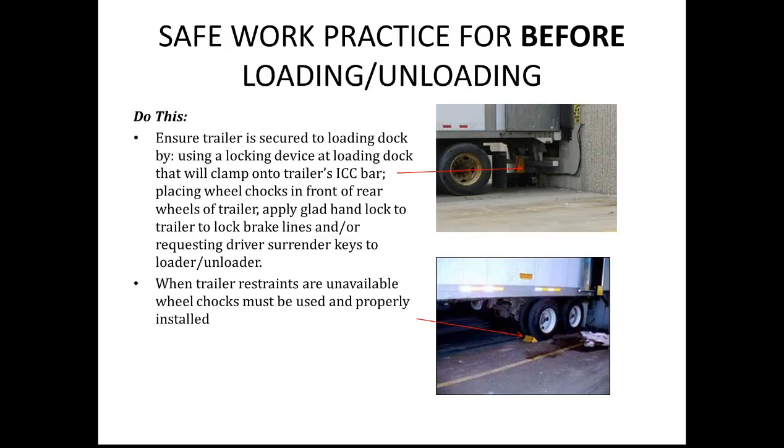The second is that you can place wheel chocks, and you see where that steel wheel chock is in the second picture. It's put behind the second tandem axle. That's where you put them, okay? And there's a reason for that. It's because it's much harder to pull over that if a driver's leaving the facility.